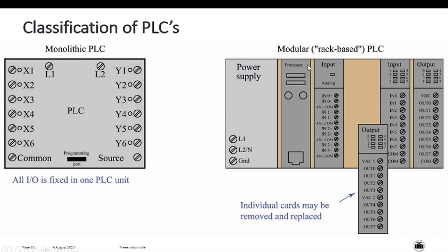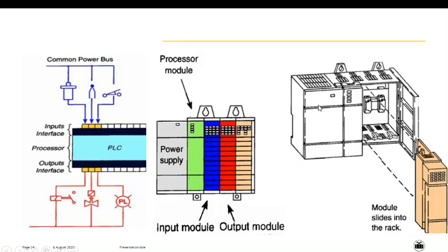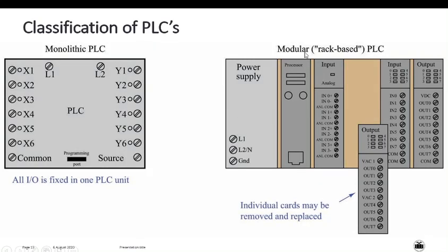And there is another type of PLC, which is the modular PLC, which we can expand as per our requirement. In this there are again certain types: small size PLC, medium size PLC, large size PLC, nano PLC, etc. In this modular PLC, the processor is fixed and it is of higher configuration. Whenever we require any kind of expansion, in this case we can add the inputs.